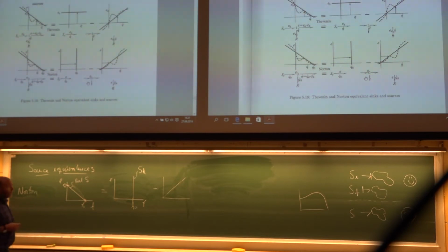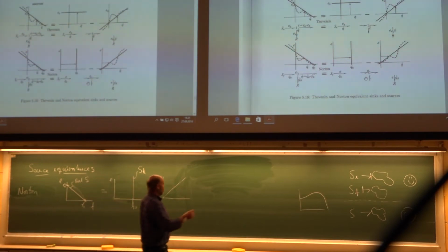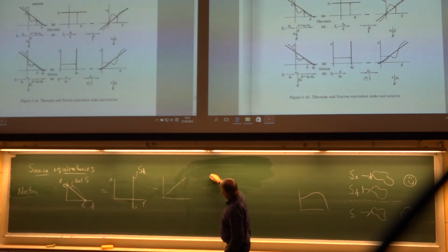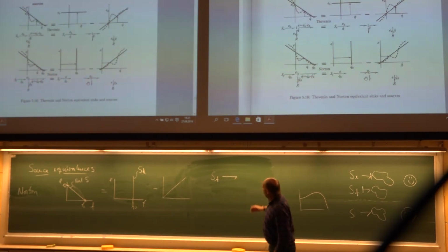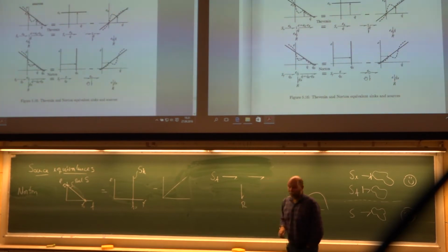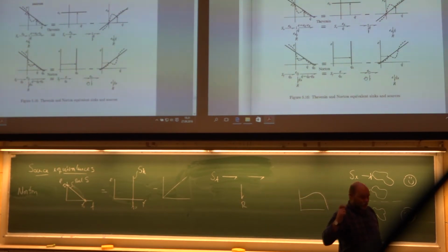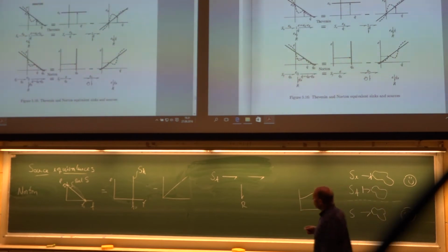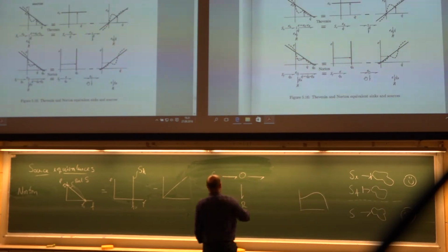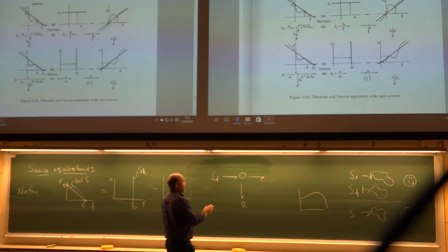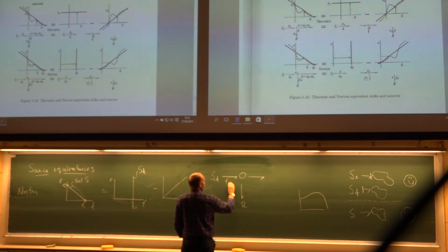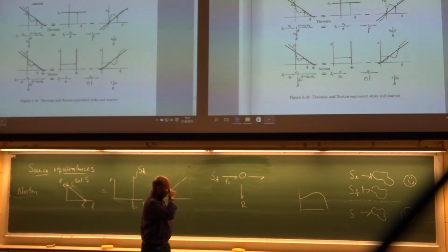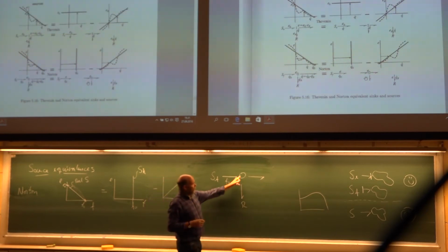But here, to obtain a source, so now you have a flow source hitting, and what should it be on the other side here? You will now have a difference in flow. Then you use the common effort junction to describe this. So here you will have your F0, and it's a common effort.